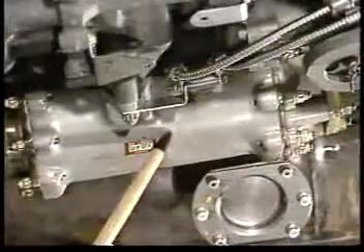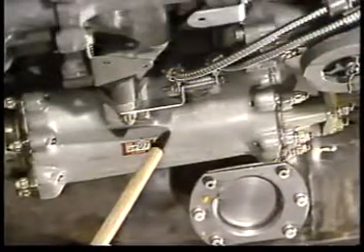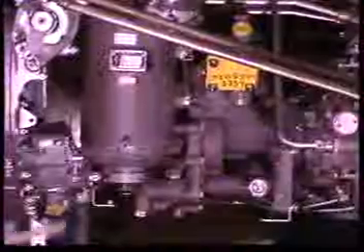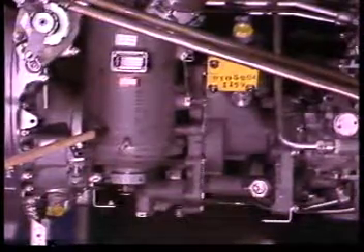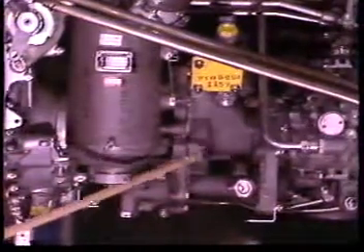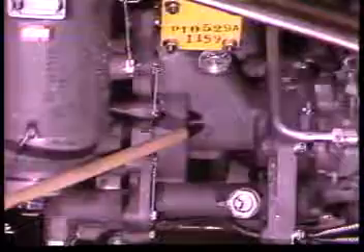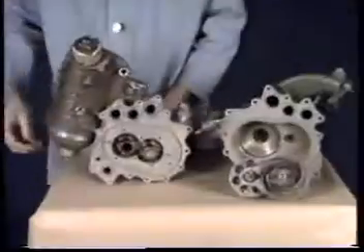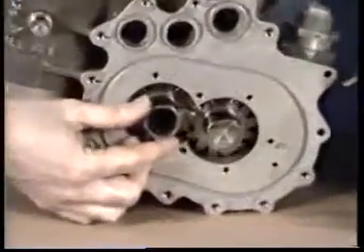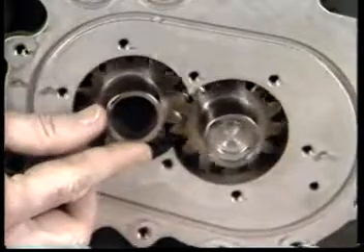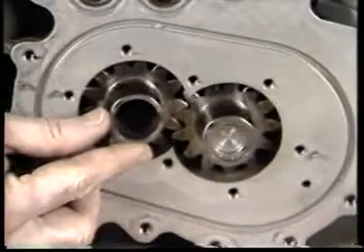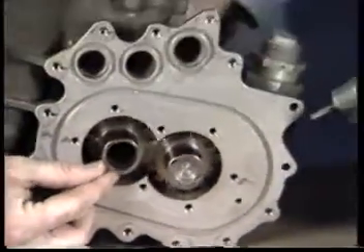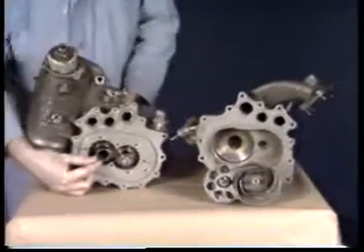The pump delivers fuel to the fuel heater. From there, it goes to the fuel filter and pump main stage. The main stage of the pump is a positive displacement gear stage. It provides additional pressure rise and delivers the pressurized fuel to the fuel control.